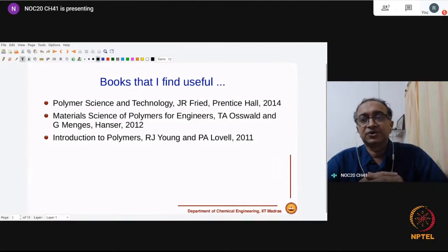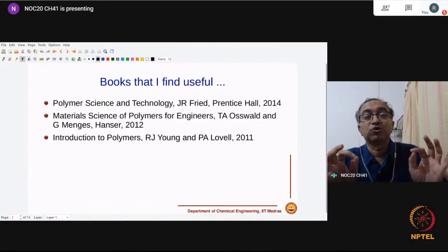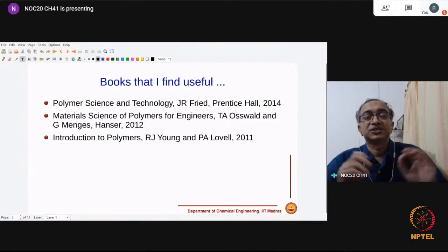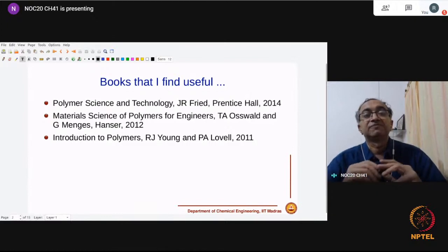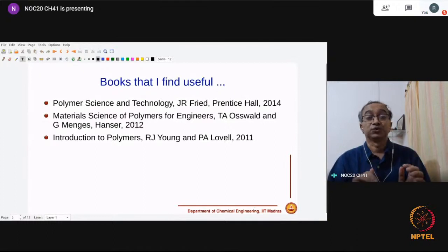And cross-link density is basically related to the chain or polymer segment which is between two cross-link points. Cross-linked polymers are network polymers where covalent bonding is quite often there, and between these covalent cross-link points, the chain is free. So what's the length of that chain? If it's a very high length, that means the cross-link points are very few, which means cross-link density is less.